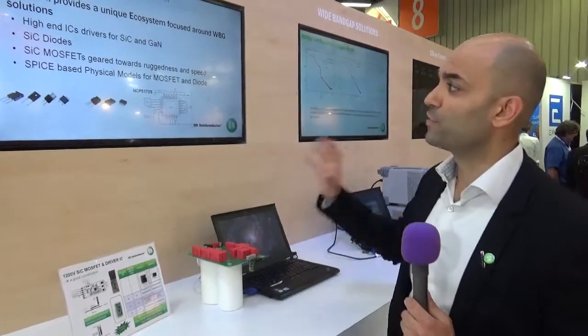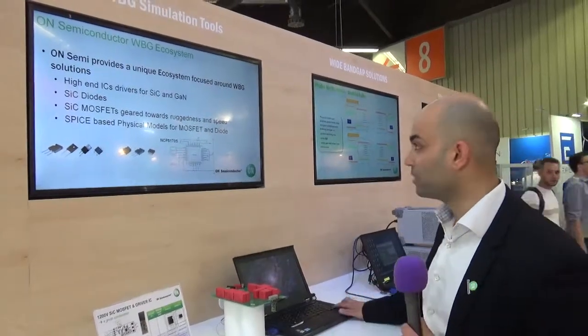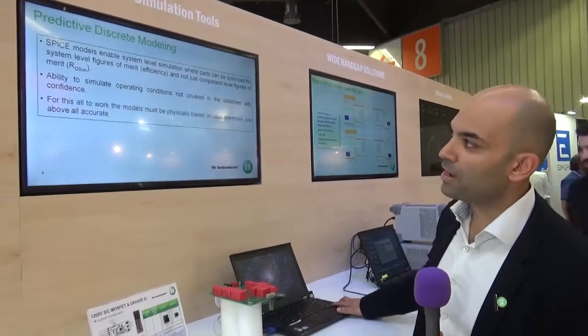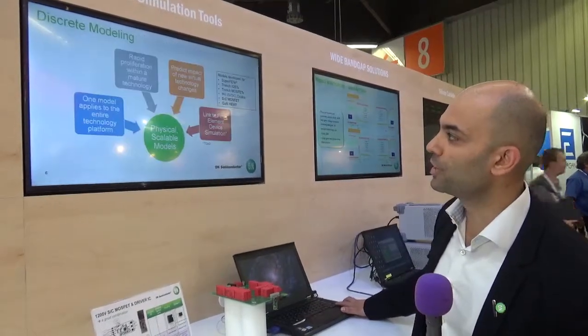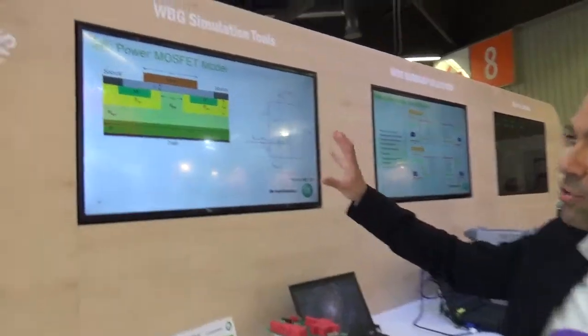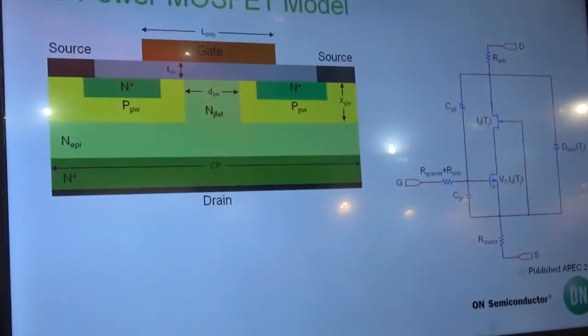Then our physical models enable customers to quickly prototype within a virtual environment, and not one that gives you just your SPICE model. This is something totally different. I'm not going to run you through all the points. Where I want to come to is how such a physical model is built up. Typical models in SPICE use the built-in MOS model or something. People do curve tracer extraction, they populate parameters, there you go. These models are by far not what you want to do for system simulation.